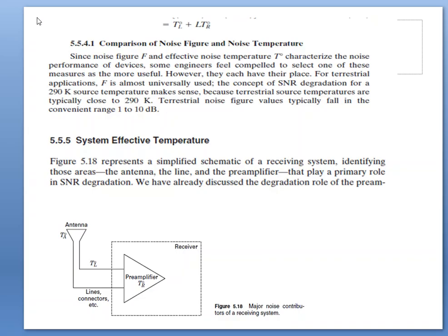We have discussed that in a lossy line, the signal is attenuated while the noise is held fixed. The remaining sources degrade the system from both natural and man-made sources of noise and interference that enter into the receiving antenna. Natural sources include lightning, radio sources, atmospheric sources, and thermal radiation from the ground and other physical structures. Man-made noise includes radiation from automobile systems and other electrical machinery, and radio transmissions from other users that fall within the receiver bandwidth.